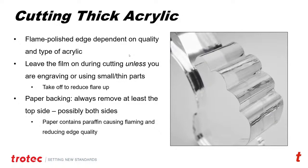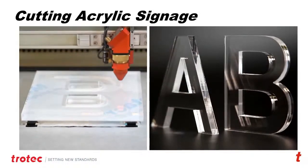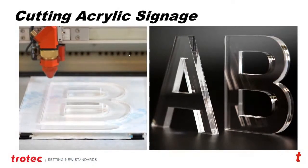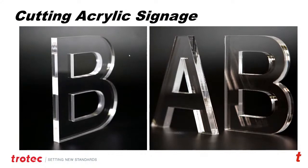Thin acrylic is not that big of a deal. It's not a problem at all. Most wattages can cut it, but as you get into thicker acrylic, I do suggest maybe looking at my laser hacks. I have one coming up which really goes into details of cutting different acrylics. So here's an example of a 1/2 inch thick piece of acrylic cutting real quick. Of course, this is in time lapse. It is not this fast. It is elevated over a wet paper towel. That'll reduce your flames. That's one of my hacks that I produce. Works very well to keep any flame, and you get that nice finished flame polished edge when cutting acrylic.